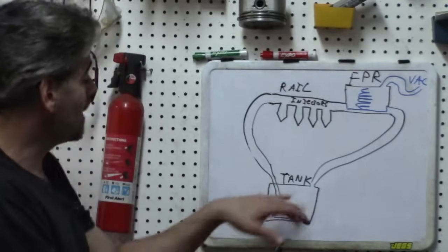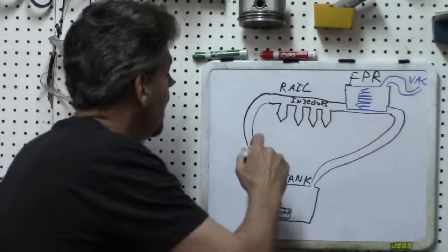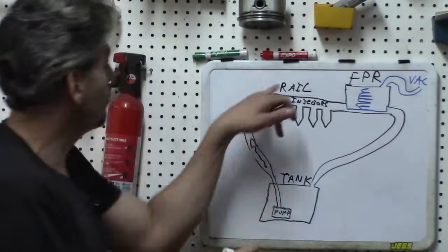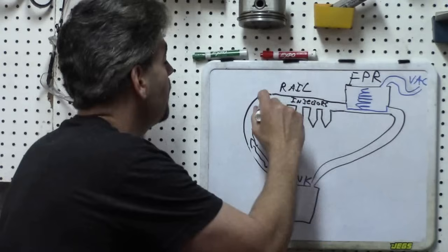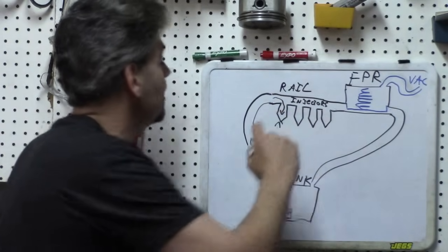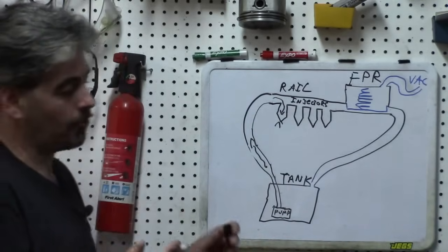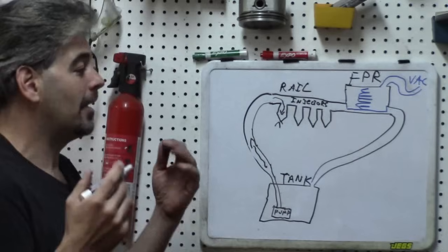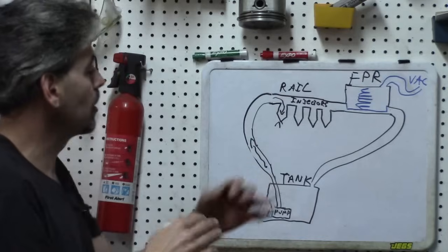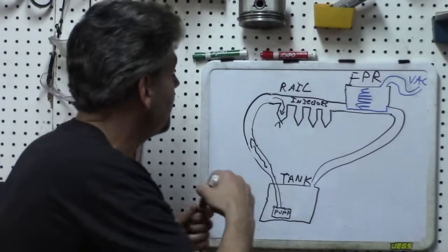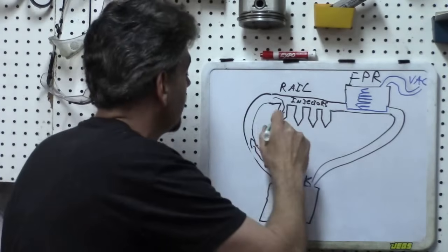Basically, here's your fuel tank. You have your fuel pump, which of course drives up fuel to the fuel rail. You will have your injectors here, and of course the fuel goes through the injectors. The injectors deliver fuel into the intake manifold, and to be specific, there are newer designs called direct injection, where the injectors deliver directly to the cylinder. We're not really going to cover that, but let's actually put fuel in green here so it stands out a little bit.